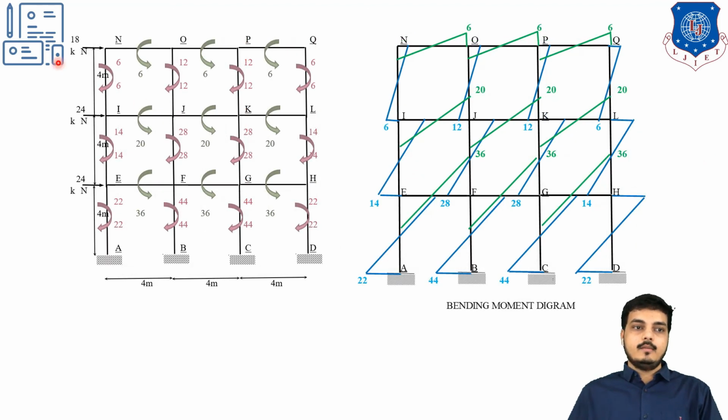After shear force, the bending moment. So this is my column moment. Here it will be drawn from the point of contact, with tension at the mid height, which we have assumed. So here it is 6 and then it will go toward 6 as well. So 6, 12. Over here, the blue one is for column moment and this all is 6 value for the beam. Similarly, for all we can find out. You can assume this as outside and this as inside. Whatever you assume, just follow it uniformly for all. Right now we are not keeping any positive or negative side.